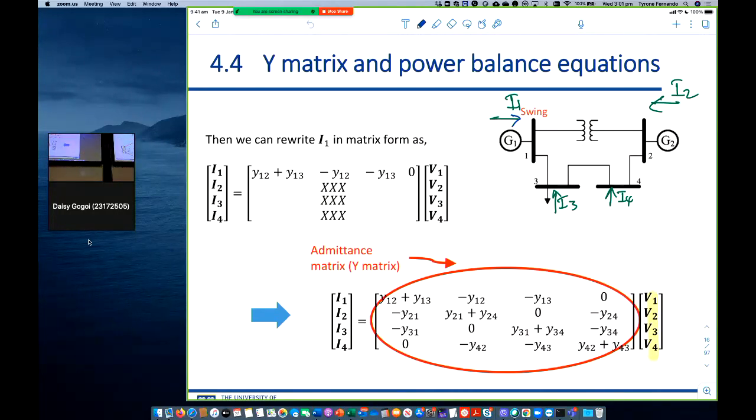Once we know all 4 parameters for each of the nodes, then we can calculate other information of interest, for example line losses, and the voltage magnitude and angle at load buses. Information that is unknown to us, we can determine once we've done a load flow. In the last lecture, we stated that based on the information that we know about a particular node, we can classify that node.